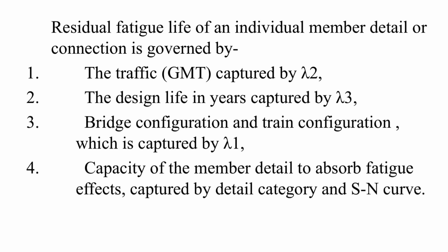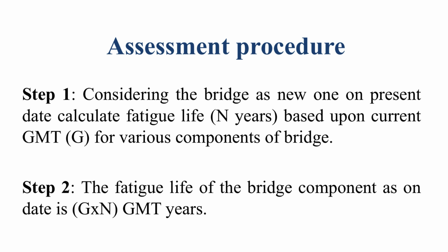The design life is being captured by lambda 3, bridge configuration and train configuration are being captured by factor lambda 1, and the capacity of the member to absorb fatigue effects is being captured by detail category and SN curves. With this much technical background, we can now come to the steps involved in assessment of residual fatigue life of a bridge.